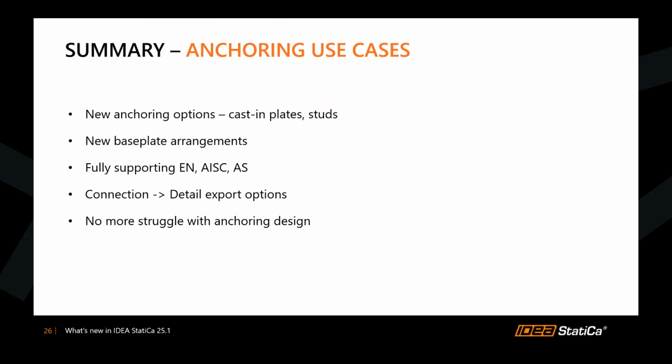Steph demonstrated on Eurocode, but we also support AISC and ACI for detailed 3D American codes, and for Australia AS 3600 as well. So this anchoring workflow is available for users of all three code families. Also, we are adding more connection to detail export options.